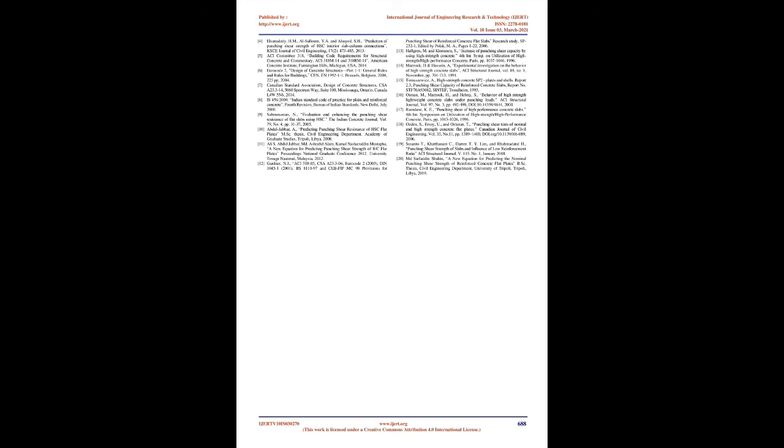The provisions of the North American codes ACI 318-14 and CSA A23.3-14, which are based on the same expression, do not include the influence of flexural reinforcement. The proposed equation, which is based on regression analysis using an expert software program, depends on results of specimens from different studies and includes the influence of the flexural reinforcement ratio.